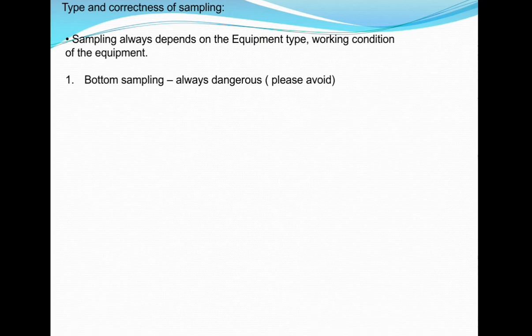So sampling types, we'll see the bottom sample. It is always dangerous. Never take a sample from drain points. This is the bottom sampling, meaning the drain point. You should not take it, should not prefer it. You must avoid this. Then live zone sampling.